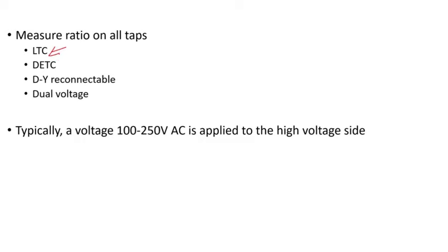So if you have a load tap changer, you know, that's a lot. It's a lot of taps, but that's the only way you can guarantee that there is no issue with the tap changer, because sometimes per tap you might only have 1 or 2 turns, for instance. A mistake might happen where if 1 turn is added, it's going to affect the results. So the only way you can check that is you perform the test on all taps.